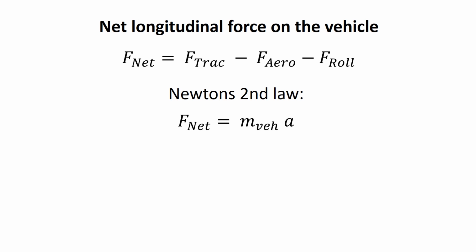Once we know the traction force and all driving resistance forces, we can calculate the total net force in longitudinal direction. Newton's second law tells us that the net force is equal to the vehicle mass multiplied with the vehicle acceleration. We can use this to control the acceleration by controlling the net force.